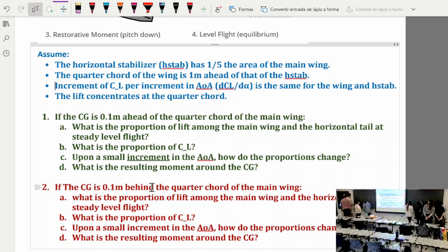If they both increase by 0.1, 1.1 becomes 1.2. How about this? Minus 0.4. Will this change or not? This is going to change. It's going to become even more negative, actually, right? No, this will become positive 1.2 over negative 0.4. The main wing is positive. The airplane wouldn't be flying if the main wing were negative.